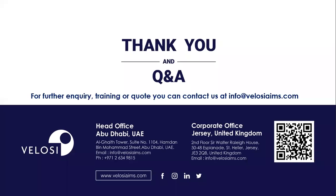Okay. Next question from Mr. Swapnil. I am working on a gas processing plant, GPP. Our F&G detection system is initiating ESD on fire detection, which in turn automatically initiates ESD plant shutdown. In this case, should the F&G SIS be considered for SIL classification? We have already considered SIL2 for the F&G ESD. However, the client is asking for SIL3 ESD. Is it required to have SIL3 on the F&G system ESD?